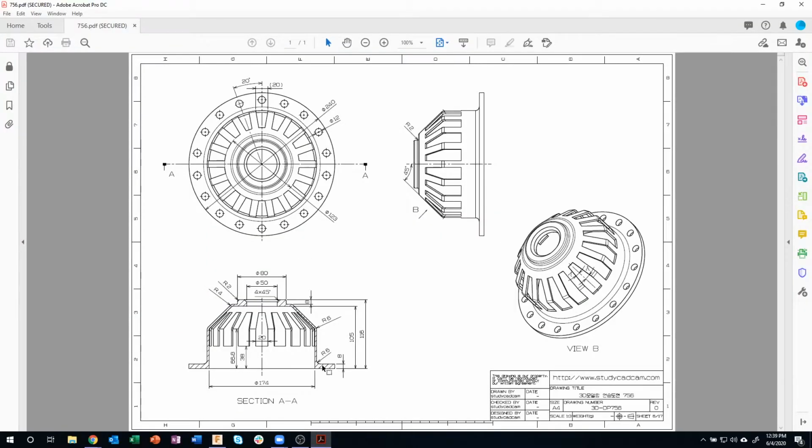So I know it took a couple steps. I could have drawn my profile to have basically this shaded in area, this hatched area. I could have drawn my profile like that and then revolved it around and it'd be hollow on the inside. But man, I would have had to have a lot more dimensions. I'd have to have some chamfers. I'd have to maybe offset some faces and stuff like that. There's absolutely nothing wrong with doing it 3 different ways. Use the shell command. Don't use the shell command. Try a complex sketch. Try a simple sketch. Can I get to the same spot using a couple features instead of a 20-minute sketch that I've created?